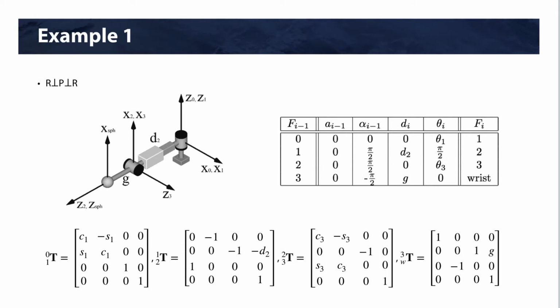In this video, we're going to look at the example of a main arm, which is comprised of 3 joints. It's a revolute joint, perpendicular prismatic joint, perpendicular revolute joint. So here we have joint 1 revolute, joint 2 prismatic, so this translates in and out, and we have joint 3 revolute. It's connected to a spherical wrist here. So we'll make a note. This is our spherical wrist.